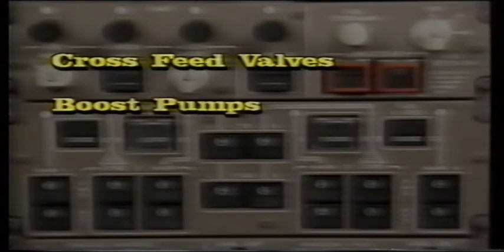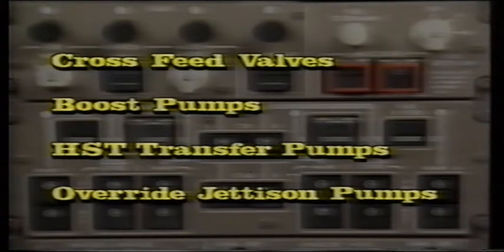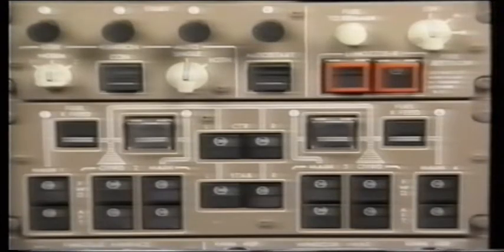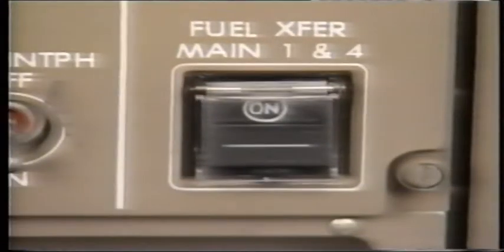Control panels on the flight deck provide operational management of the fuel system. The fuel management panel supplies direct or arming control of the cross-feed valves, boost pumps, HST transfer pumps, and override jettison pumps. Lights and flow bars on the fuel management panel are used to show system status and configuration. A fuel transfer switch allows manual control of the fuel transfer valves which connect the outboard and inboard main fuel tanks.